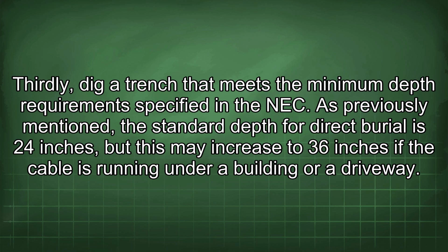Thirdly, dig a trench that meets the minimum depth requirement specified in the NEC. As previously mentioned, the standard depth for direct burial is 24 inches, but this may increase to 36 inches if the cable is running under a building or a driveway.